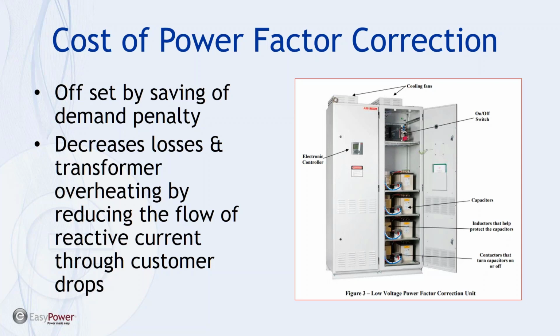Also, it actually involves some significant power or energy savings, because that extra current, even though it was reactive, didn't have to flow back and forth through the utility pipeline, if you will. And even inside of my own plant, if I located the power factor correction near the large motors that were drawing or creating the reactive demand, it reduced the losses inside of my plant as well.